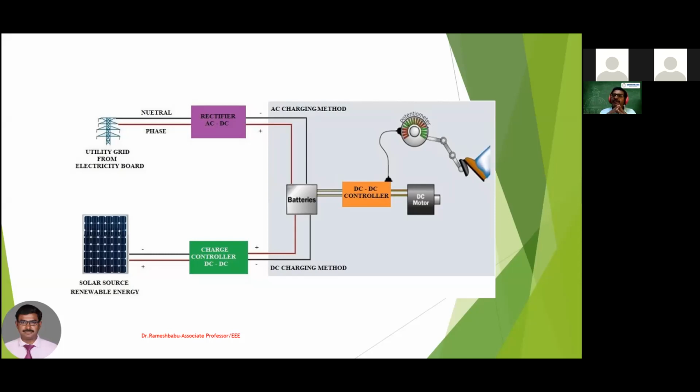In a similar way, I can have an AC based electric vehicle. There will be only one difference. From the battery, instead of the DC to DC converter, I can use a DC to AC converter, and I can use an AC motor.